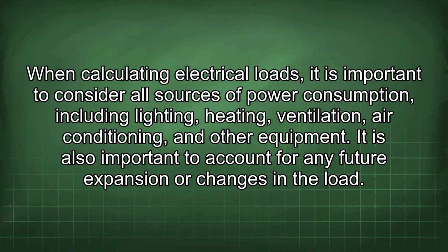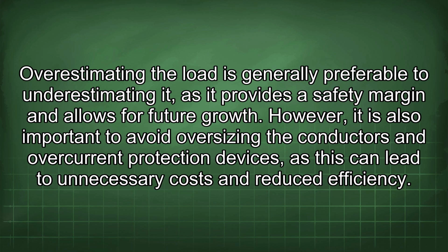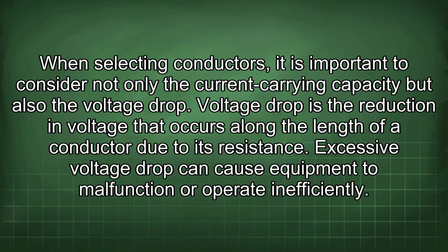When calculating electrical loads, it is important to consider all sources of power consumption, including lighting, heating, ventilation, air conditioning, and other equipment. It is also important to account for any future expansion or changes in the load. Overestimating the load is generally preferable to underestimating it, as it provides a safety margin and allows for future growth. However, it is also important to avoid oversizing the conductors and overcurrent protection devices, as this can lead to unnecessary costs and reduced efficiency.